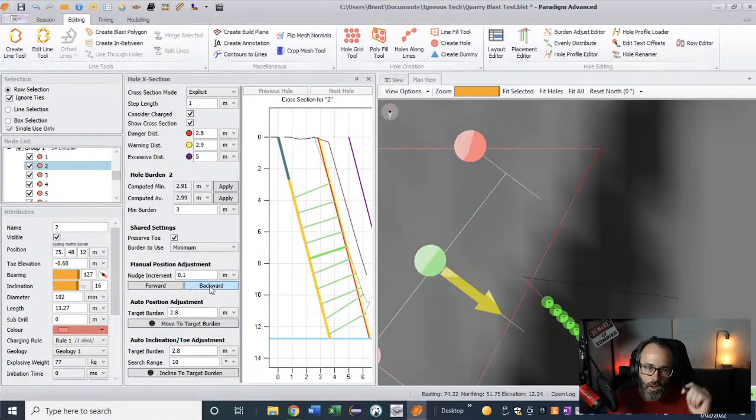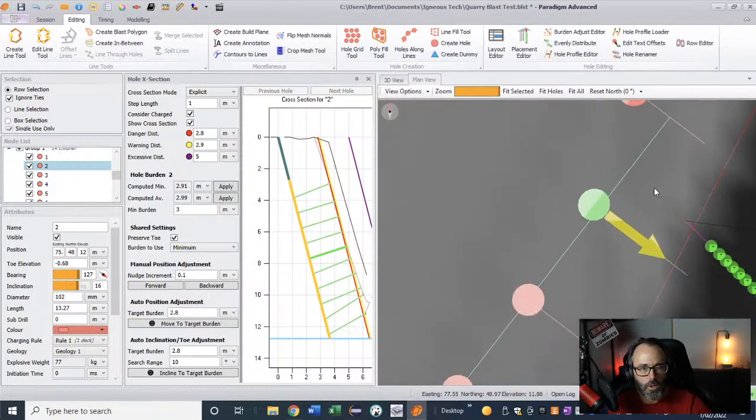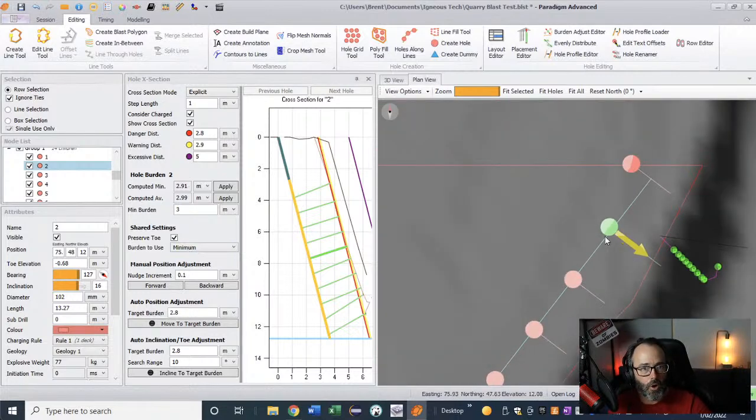So this is now the chainage, your chainage of 3.6, and it is 0.2 behind. Right? This is how you just go along your baseline and measure off the baseline, 200 mil back or forward 200 mil, or whatever the baseline suggests. So this is how you get your placement correct on your blast holes. And so we can go along and do all the holes.